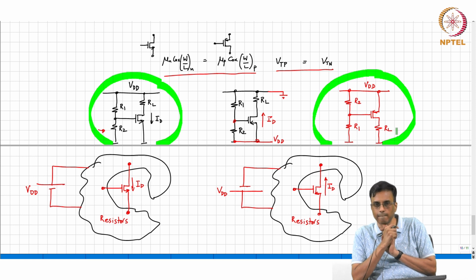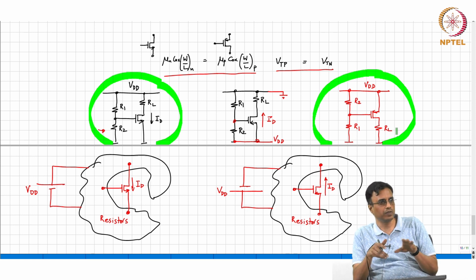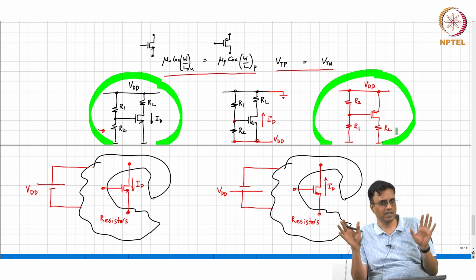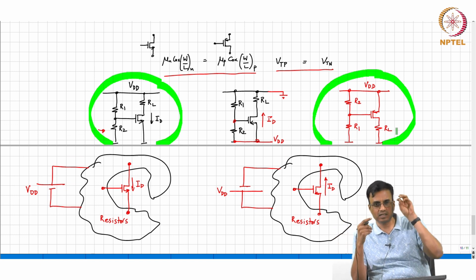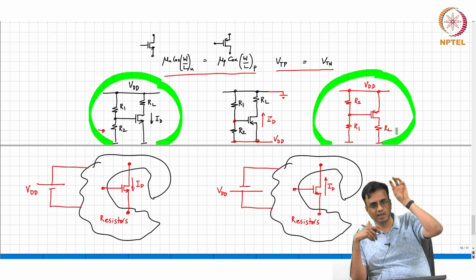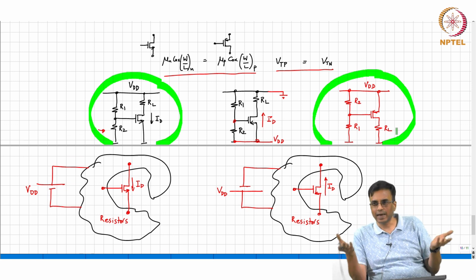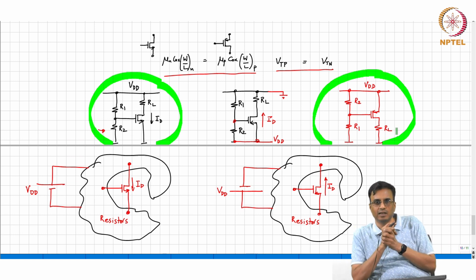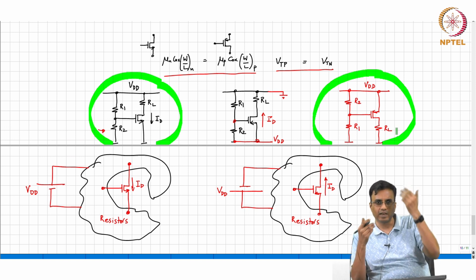And that means that the moment you see a circuit with NMOS transistors, you can convert it into a circuit with PMOS transistors by simply, first, replacing every NMOS transistor with a PMOS transistor, and replacing all positive batteries with negative batteries. Then you don't like negative voltages, so you add appropriate voltage so that the lowest potential becomes 0 and not negative.